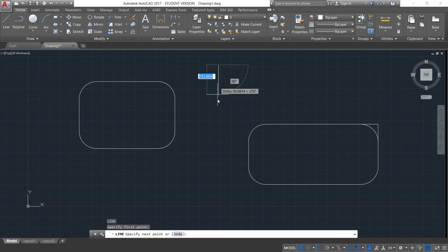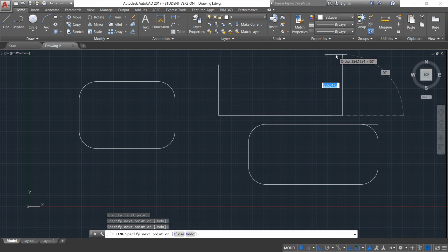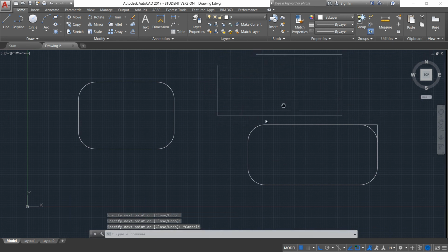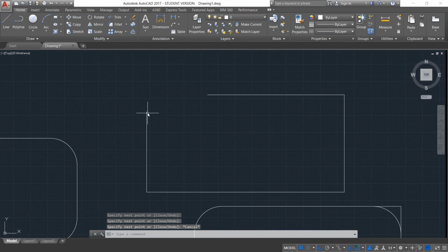Now you must think how the fillet can be used in many different ways of designing. Consider my requirement is that I want to make the line come here and this line extend here so that they join in a perfect vertex. In such a situation also we can use fillet. But how? Imagine if I give the radius as 0. Radius 0 means it will be a single point where these two lines coincide.